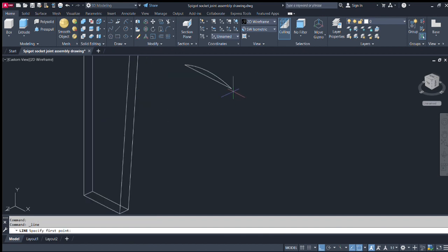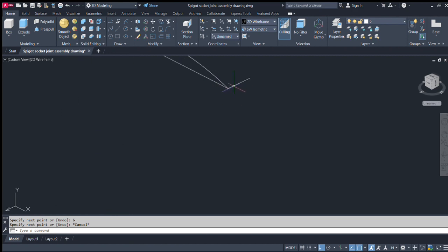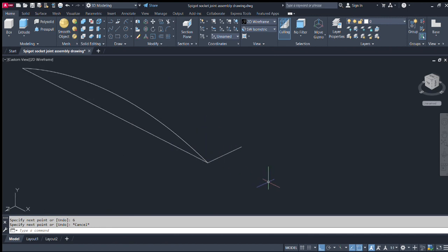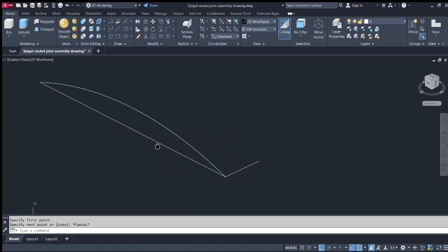So here in the z-axis I will create one line of thickness 6. Okay, because the thickness of the wedge is 6. Same goes here at the bottom, 6. Okay, now at the half I have to have a curve. But at the half I will make a vertical line in the y-axis. But what should be the length?